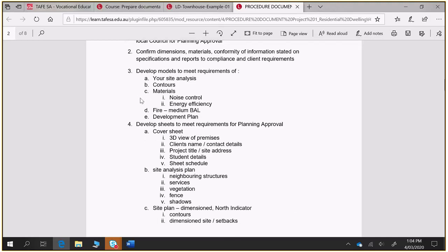Materials. So you're going to have to include materials on your plan set. Typically, your materials are going to be shown on your elevations. That's where you get to look at the face of the building and the roof of the building both at the same time. That's your opportunity to express most of your materials that are being used. Annotations, leaders, and penetrations for your materials.